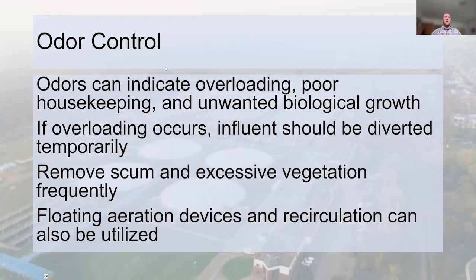Okay, odor control. So odors can cause overloading, meaning there's just more nutrients going into there. Sometimes you can divert your influent into another lagoon if you have it. A lot of times, of course, if you don't have another lagoon, that can't really happen. But sometimes aeration can help with this, or recirculation. Also, maybe you're not utilizing the full area and volume, so maybe you're having some short circuiting or something.